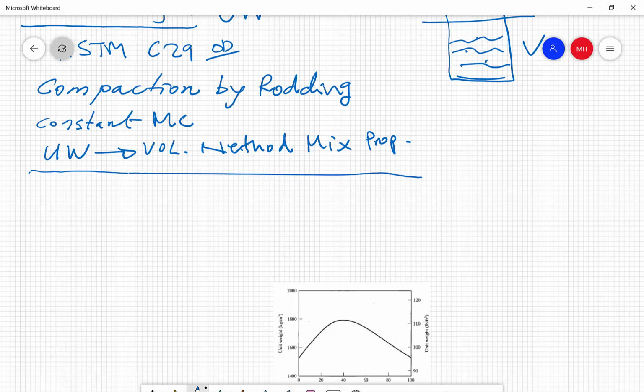All right, so the void space that must be filled with the mortar can be calculated. And again, we're talking about calculating the unit weight. We need to know the void space between the aggregates, which will be filled basically with mortar. So the unit weight in kilogram per cubic meter, which is the unit, basically is equal to the weight of the aggregate.